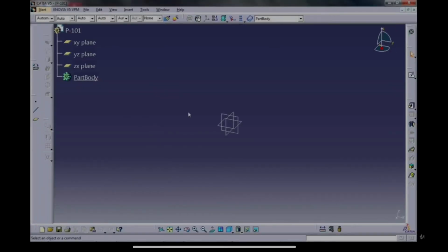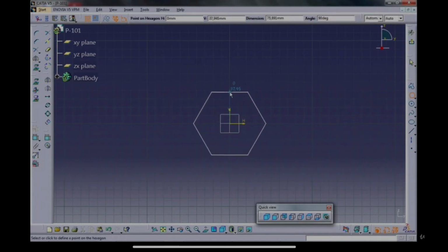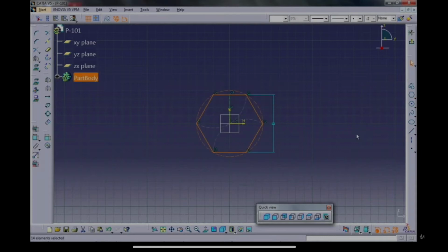Now we need to select one plane where we are going to draft our nut. So we'll take one shape, that is a hexagon, because this will give the exact dimension of a nut that we need. Now we need to take the rough dimensions. After this, as we know all the dimensions which I told you before, the outer diameter is 40 and the thickness is 10 with M20 thread. Basically we can take this as an M20 thread, but right now I'm taking diameter 20.